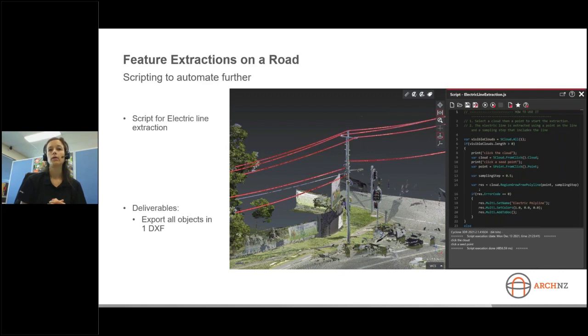If it's a bigger quarry, like if the whole site is a quarry, and obviously the sides of it are quite steep, then you probably just cannot really use the DTM function, because by default it will never create a vertical surface. So you probably have to try to clean the data in another way and then go for the 3D meshing option. So hopefully with that auto classification, that can bring a bit more ease in cleaning the data before going into the meshing.